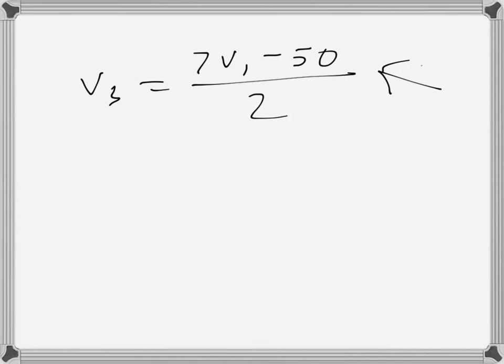I am not calculating this anymore, but for this one we didn't need to use the determinant method for solving simultaneous equations. Because of the presence of the supernode and dependent source, we could write the voltages in terms of one another, so that's why it just became one equation in the end.